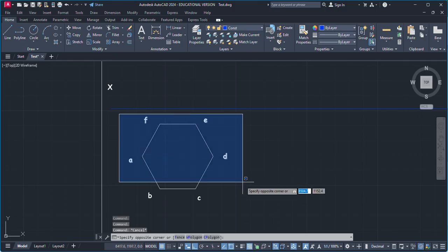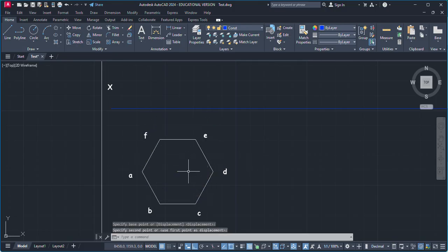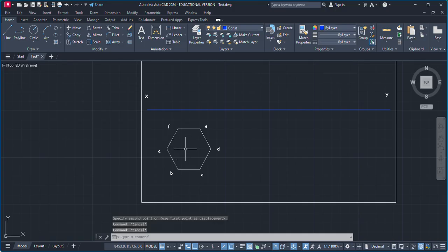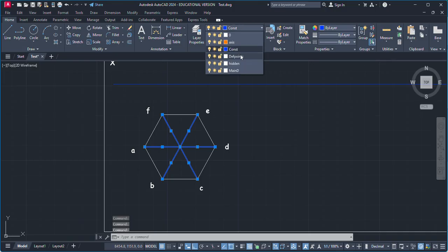So right now this thing is not complete. When our pyramid is resting on HP, this is the base face. Now from the top we will have slant edges along with the base face. So just going to draw these slant edges. They will be in solid, in the main drawing, because slant edges are visible from the top view.